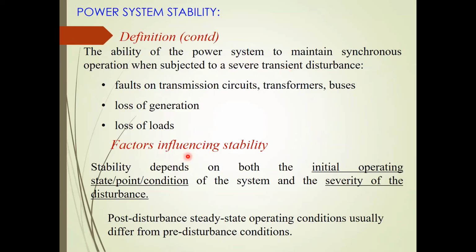So if you have a 100 MVA increase in the load, your generator will be sufficiently able to meet the increased amount of load. That is possible because the generator maximum loading is up to 1000 MVA, right? So depending upon the initial loading, the generator is only partly loaded. And if you have a sudden increase in the load by 10%, 20%, or 30%, then in that case, the generator output power can also be changed, and thereby you can have more power from the generator. So in that situation, the instability, the condition of inequilibrium will not arise.